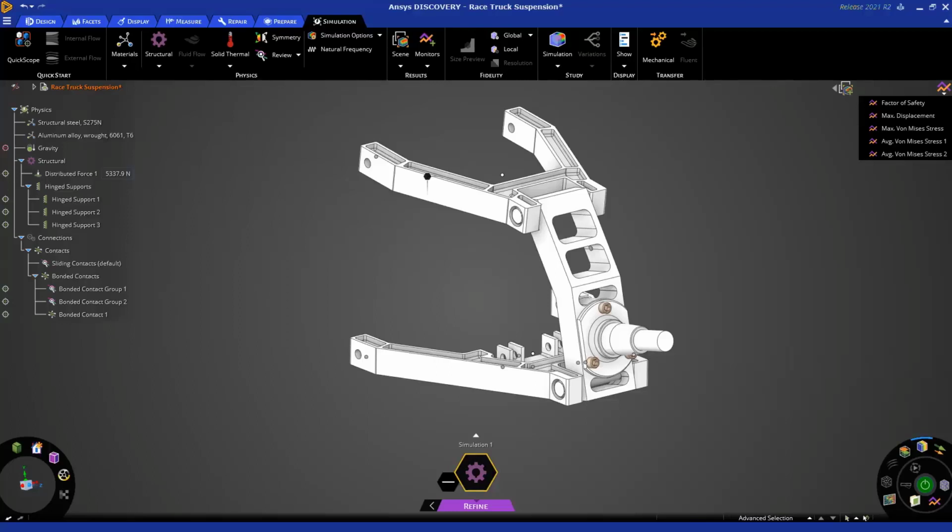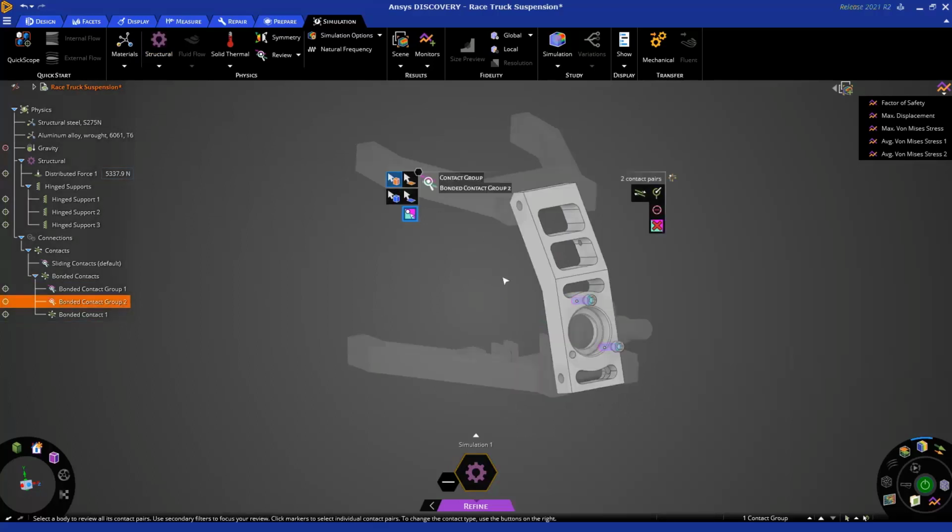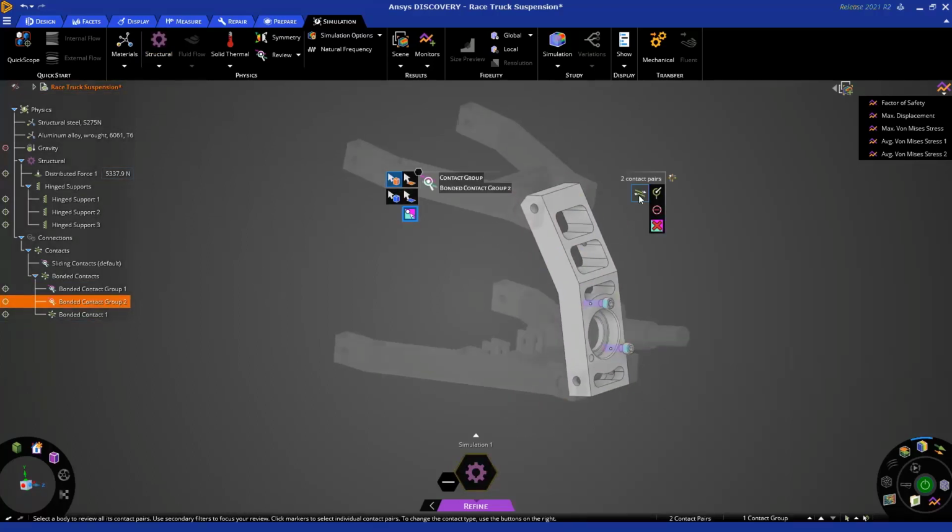In Ansys Discovery, we have our Explore mode and our Refine mode, which can be used in a variety of different ways, where the Refine is going to be a bit more traditional simulation. So as you can see up here in the top in our Refine mode, we now have access to our global and local sizing controls because we are using Ansys Workbench meshing in the background. And if I access some of my contact groups, you'll notice if I select this individual contact, I still have the same controls here. But if I select a group, you'll notice that I can have a bit more options. So I have the ability to uncheck idealize, which means I will allow separation to get a full nonlinear contact if I would like, rather than just the linear idealized frictionless no separation contact that's available in Explore.